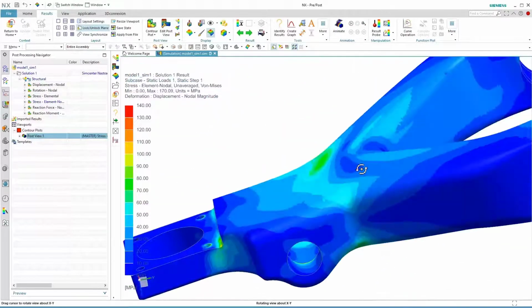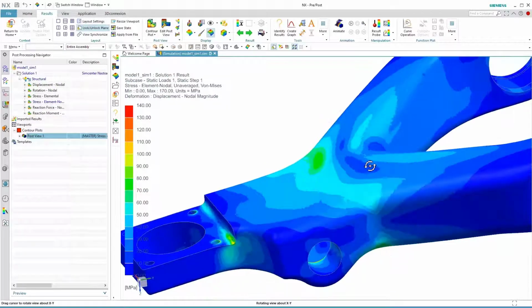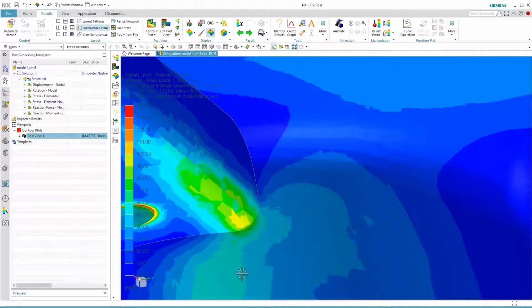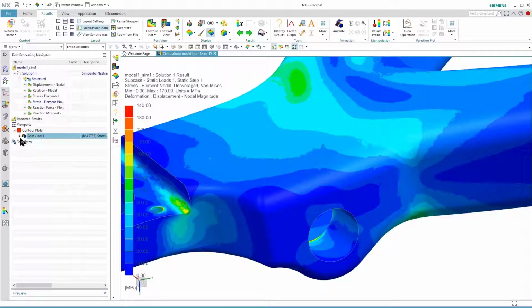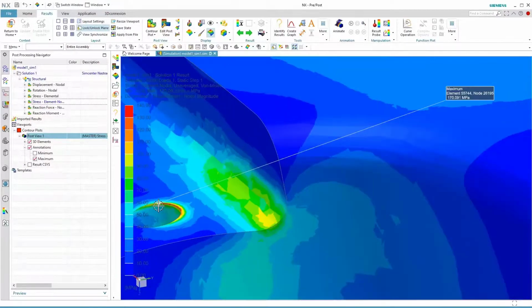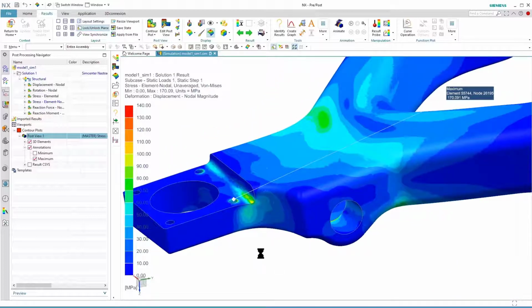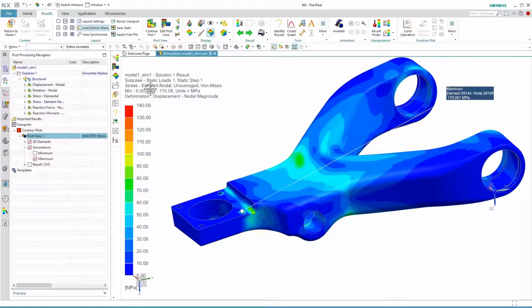It's about at the same area, just a nice line. So the convergence is also good in this area where the large stress is changing, but you see the large stress is not just there, just the annotation of the maximum, and you see where it was fixed totally rigid, the screws, there is the large stress, a singularity of stress. 170 is the maximum.